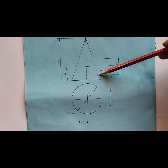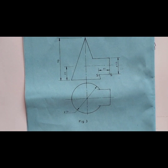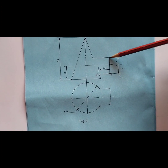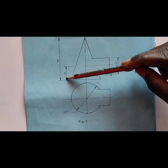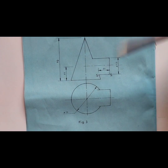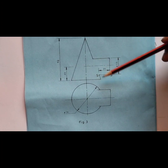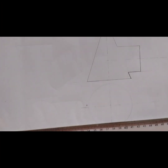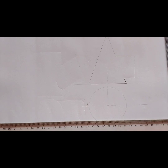Then we've been given the distance from this point S to this S as 20 millimeters, and from the base to the center of our smallest cylinder is 30 millimeters. So our first step, we are going to copy these views and draw the complete plan and line of intersection of the cone and a cylinder. So these are our views.